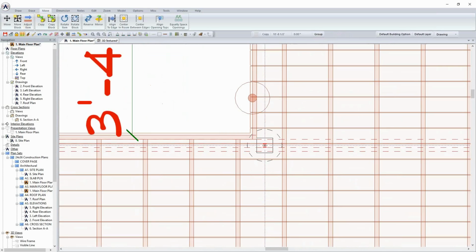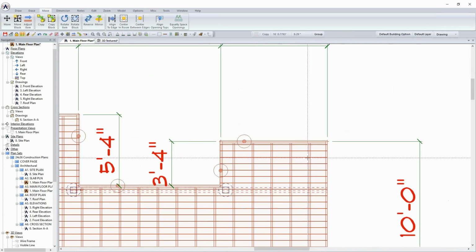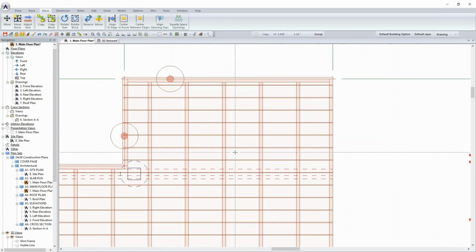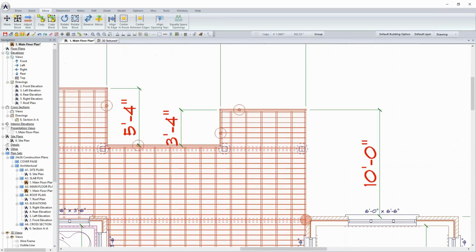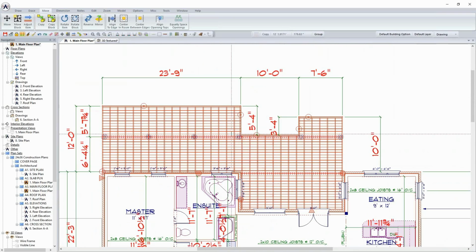And I will just simply copy a post. I can say 1 on that copy there. And then I could do a secondary copy based on the distance being 7'6". We probably just want one more over there. So simply press the copy tool. And again, I will just copy this one over to here. And again, as I say, in time, we could pull this off and pull exact dimensions. But for the planning stages right now, we're getting pretty far.